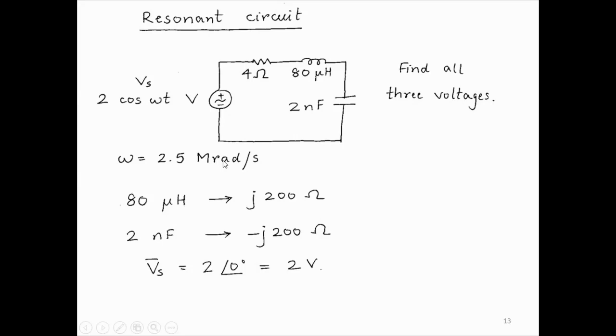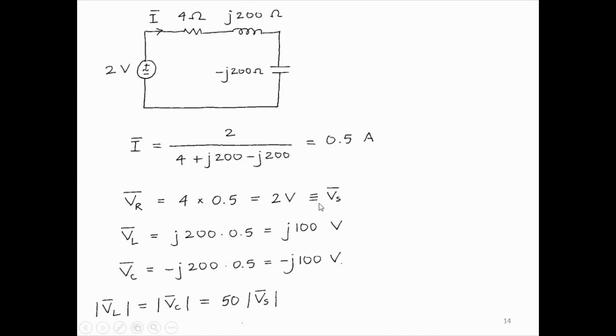The signal that you are talking at has a particular frequency, and the resonance circuit in your mobile phone is tuned to that same frequency, and so it will catch it and give an output. So this circuit will give an output 50 times what is applied to it only for that specific frequency. At all other frequencies, it will give a much smaller voltage. And so this is how the fundamental communication receiver functions. We'll look at this in more detail next week.